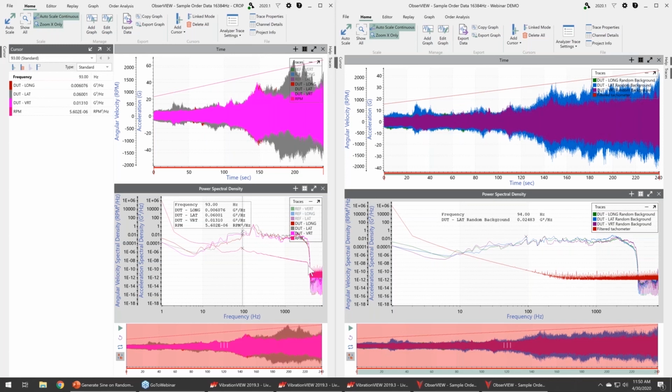All right. Next. While working on a tractor exhaust system, we have observed that accelerated time is lesser in a sine sweep profile as compared to sine on random. Accelerated time.